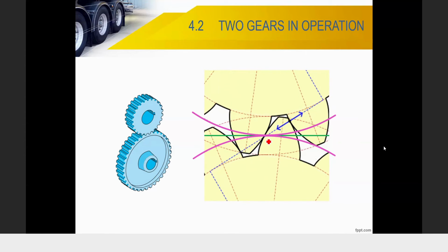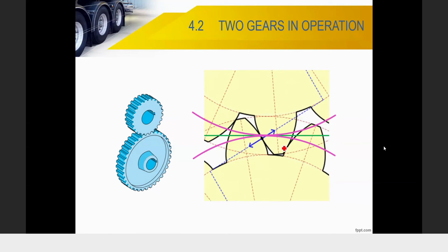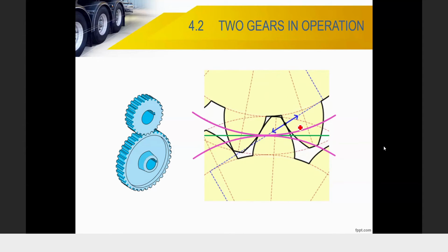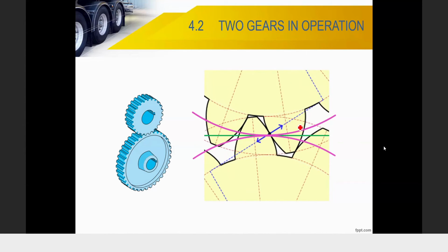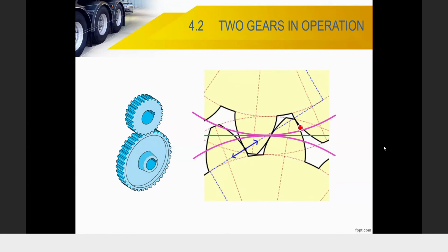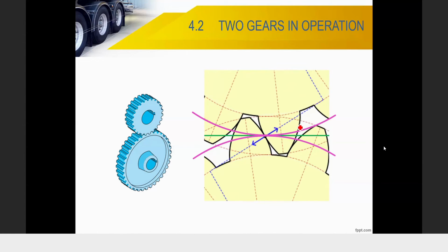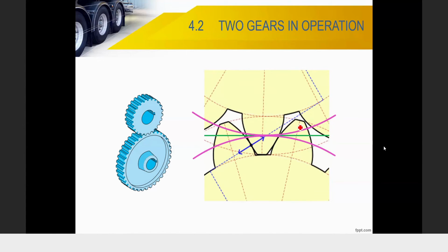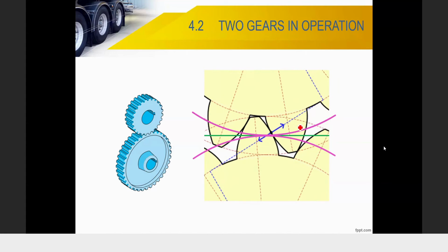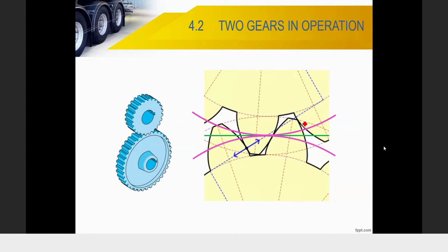The line of action remains the same. We can call it the pressure line, or just line, but normally we say pressure line. There are only two pressure angles. Gear manufacturers, like the American Gear Manufacturers Association, which has long been established, set standards based on the involute. There are only 20 and 25 degrees, no more than that. There is no other line angle, because the standard is already done with the calculation.